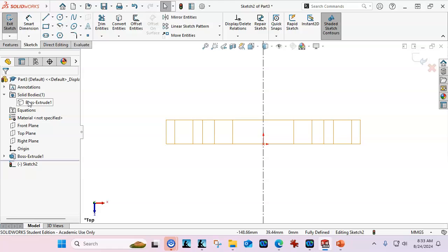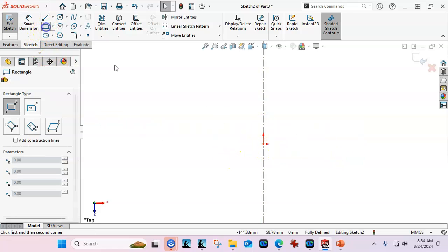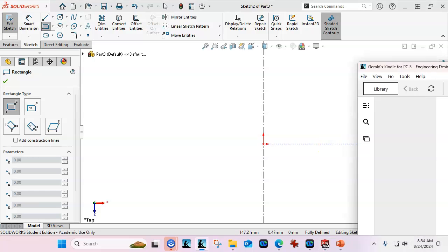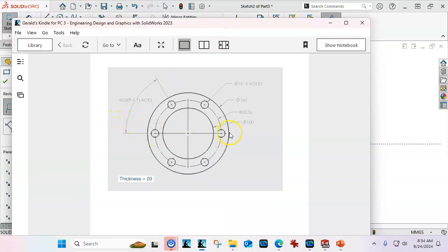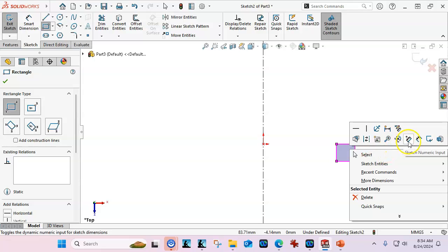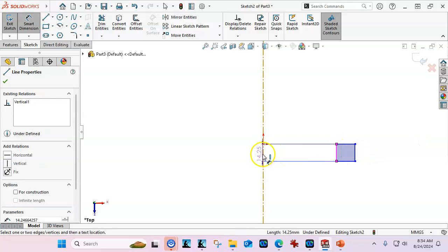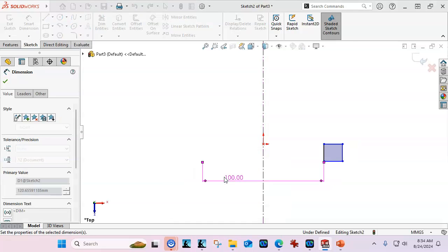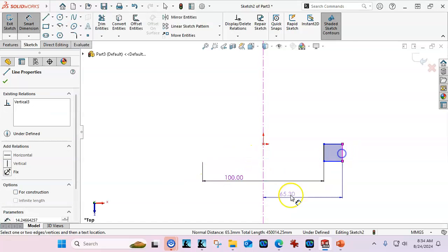And I do want to have this maybe not overlay. I want to be able to compare the two, so I'm going to draw my rectangle. So anytime we're doing a revolve, we're cutting the part in half, we're cutting that half in half, and we're looking at what this quarter section would be, not including the whole. So we're just going to have a rectangle in this case that is out some distance to the height of the extrusion and the inner and outer diameter. So that was our 100, and that is our 160.